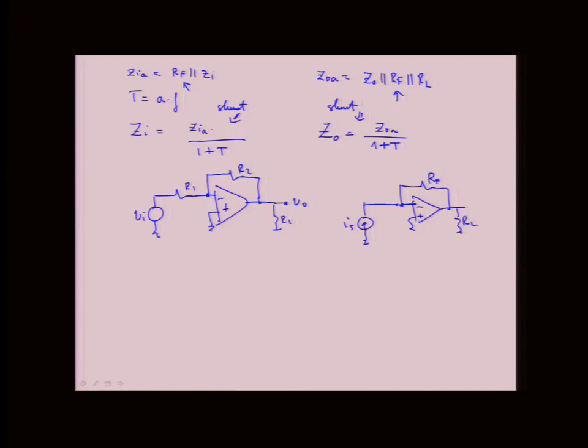You do the equivalent of VI to the current source resistor? Okay, so you're saying Thevenin to Norton type thing. So we can take this piece and make it a current source of VI over R1, and then have R1. And then that gets into the amplifier.